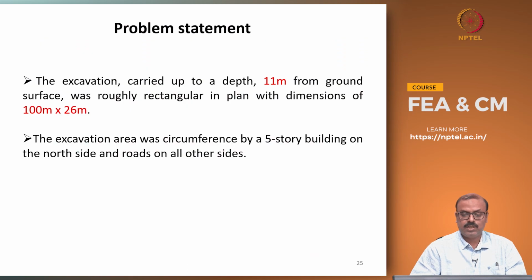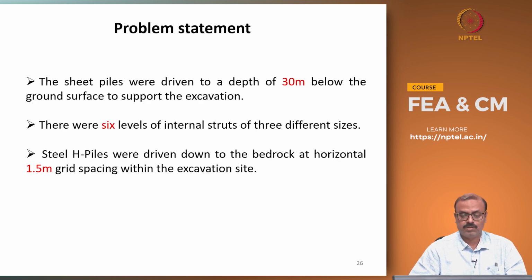The excavation was carried up to a depth of 11 meters from the ground surface, because the topsoil was a soft clay. So, you have to cross that soft clay, and you have to have a support system for that. It is quite a large plan dimension for the excavation, 100 meters by 26 meters. The excavation area was surrounded by a 5-story building on the north side, and roads on all other sides. So, again, as I said earlier, it's a very congested urban environment.